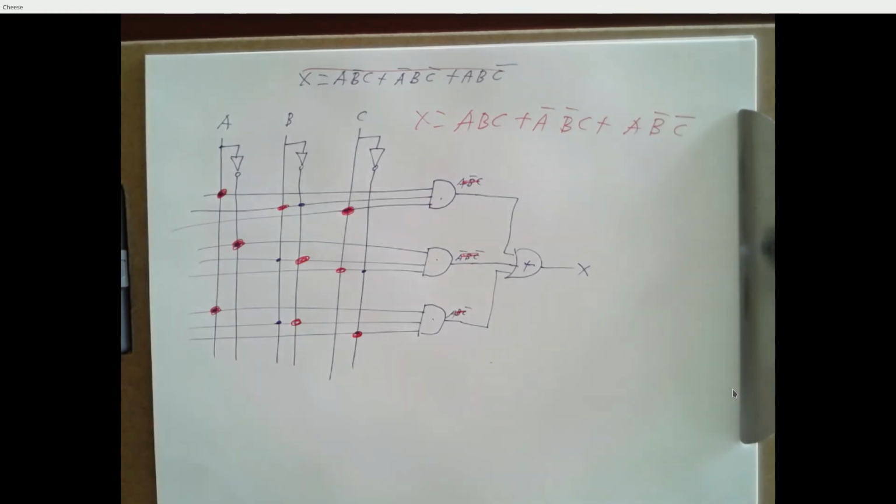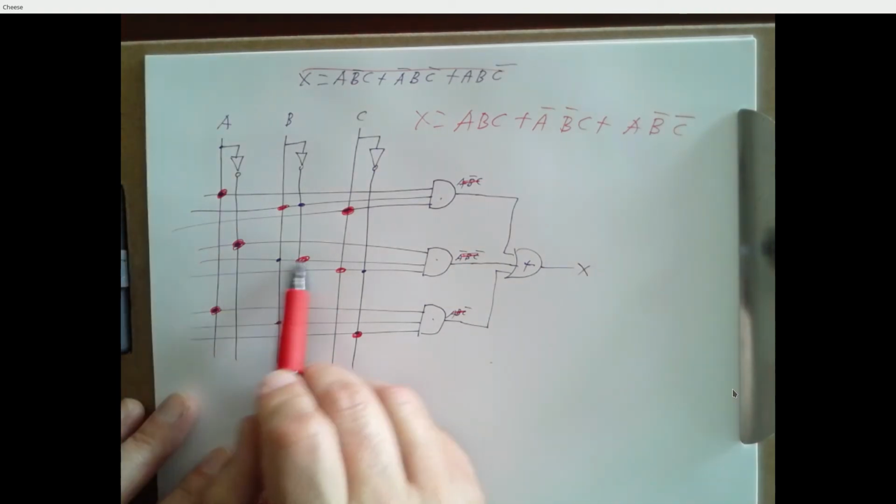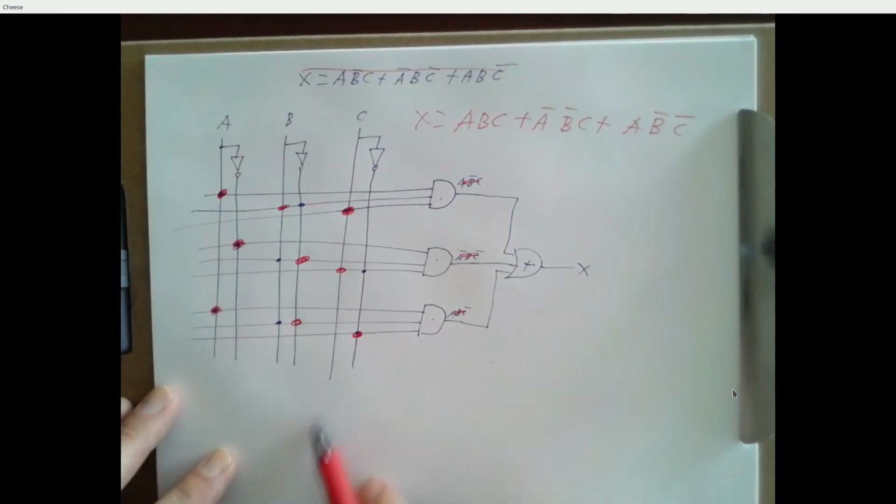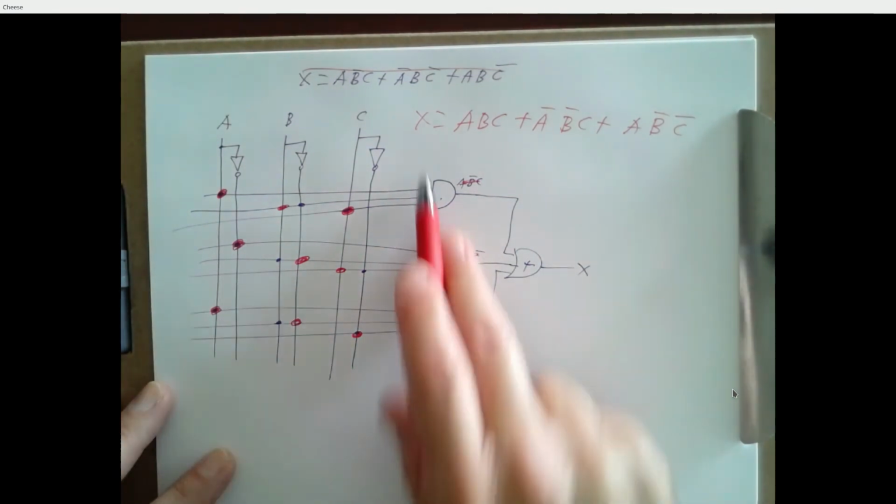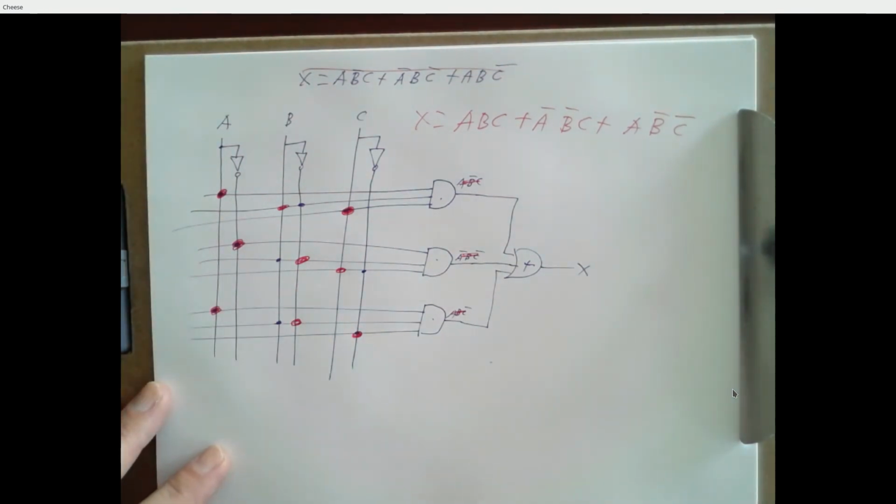So somebody very clever had the idea, what if we built a piece of hardware that basically looked like this, but let you, after this piece of hardware was in your possession, control which connections you made over here between these inputs and the inputs to these AND gates.